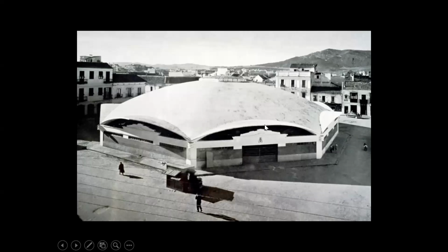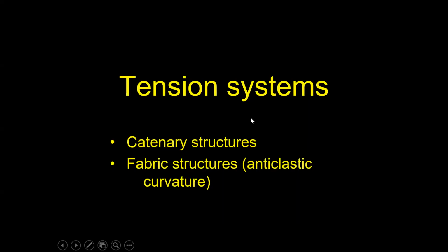And at the edges of the shell, you can see these arch shapes. Well, they require tension members to stop the arches from spreading out and from collapsing. And so all around the perimeter of this particular shell structure, we require these tension beams, just acting in tension to give strength to the shell roof structure. So those were structures that rely on compression.